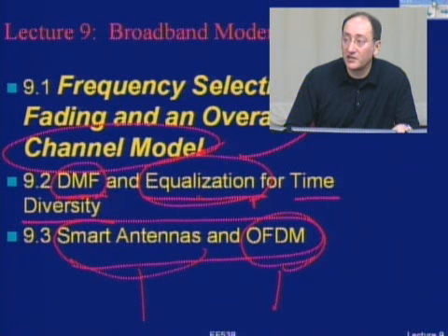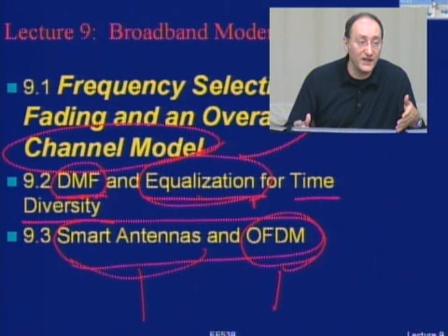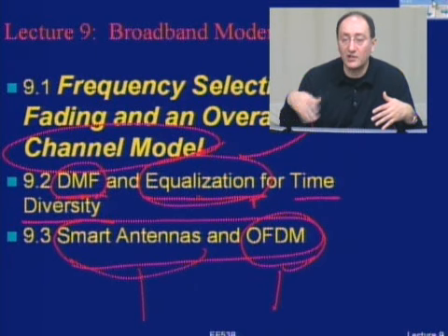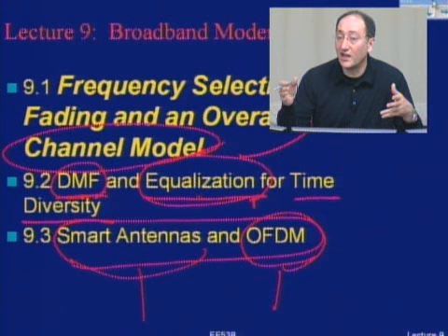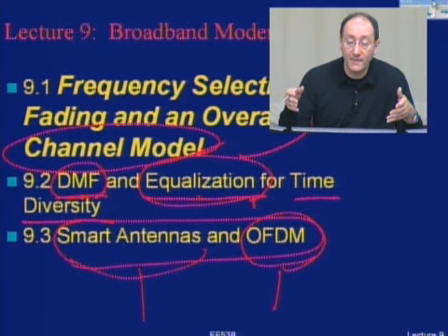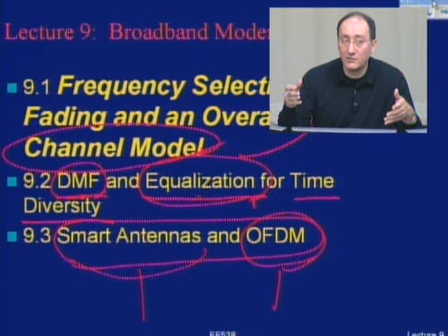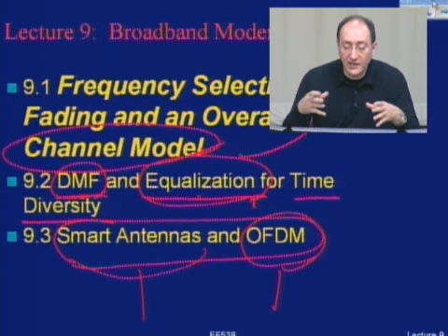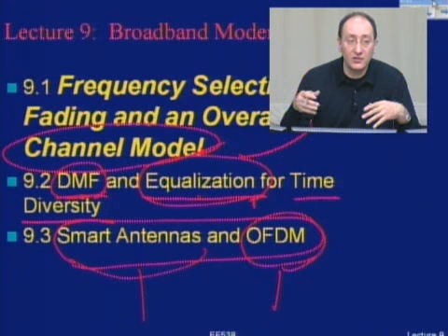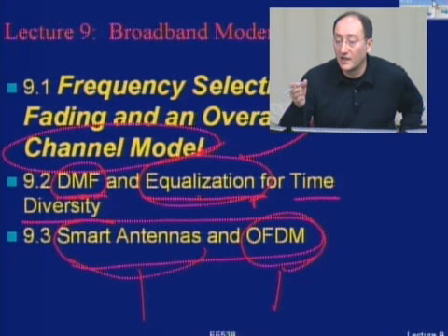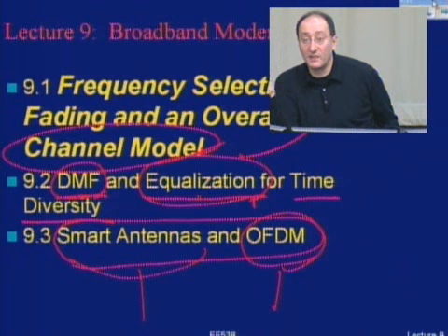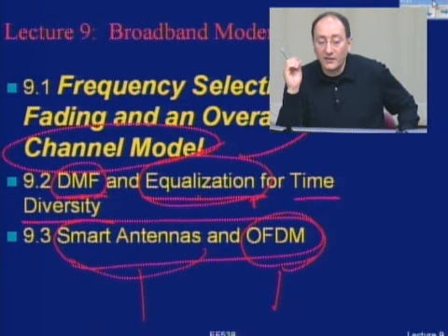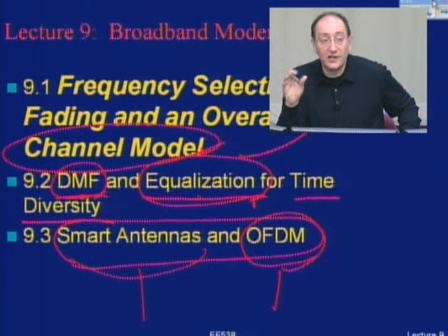If I have a voice application, I have an encoder which is like 10 kilobits per second. The data rate is fixed. What I need to do is increase the capacity, which means I have to change my medium access control. But when I have a single-link modem for a data application, like wireless LAN or mobile data applications, my medium access control is like carrier sense multiple access, or a random access, or could be TDMA. But for one instant of time, I want to have very high data rates.